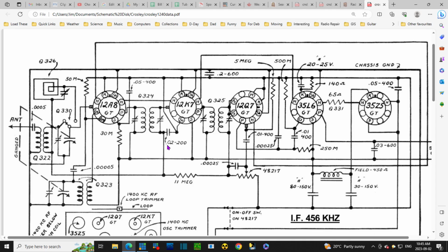But if you don't have this capacitor, then the only way to ground is through this guy and through a bunch of stuff, and maybe you never make it there really. So this guy's purpose is maybe not so much to dampen the AVC, maybe more to provide a signal ground on this side to make this antenna work.